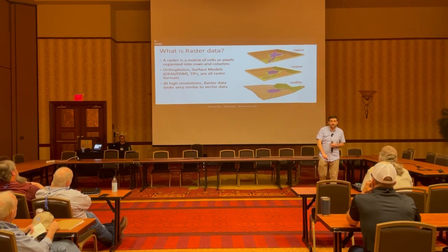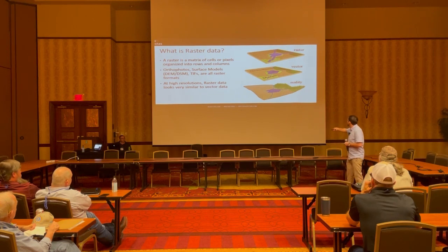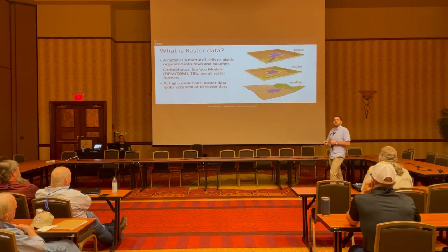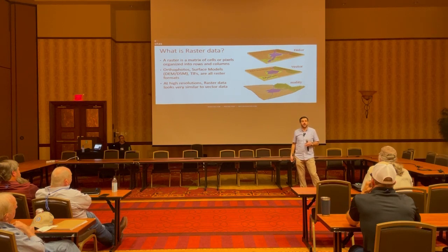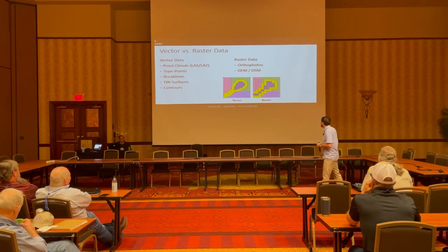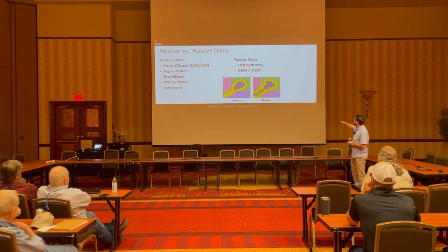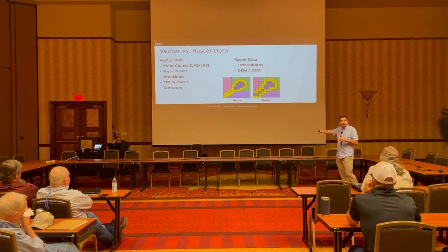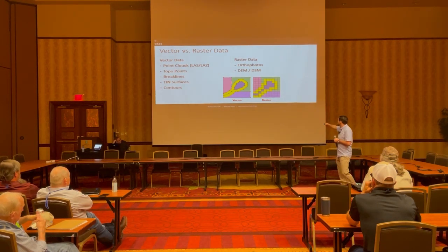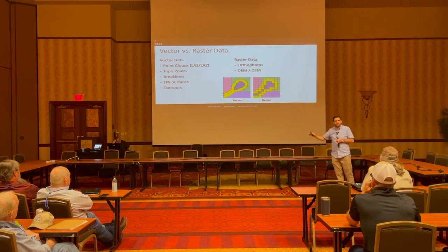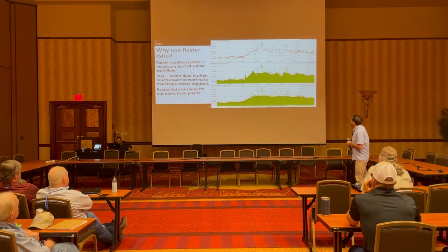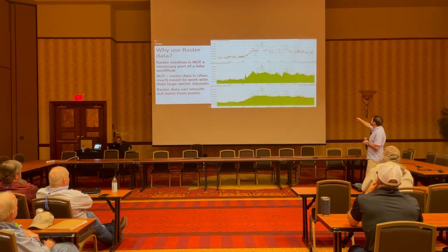Well, you take vector data, which is LiDAR data, point clouds, and this is what vector data would look like, kind of angles, and you turn it into raster data. This is turning it into a picture or a map, what you're used to looking at, where everything is broken down into pixels. The way to do that is you take a statistical average of your vector data and you turn it into raster data. Now this looks ugly, and because it's super zoomed in, you say, well, this looks so much nicer. And yeah, that's true, but it's more just to illustrate what it means to actually bin things into these pixels.